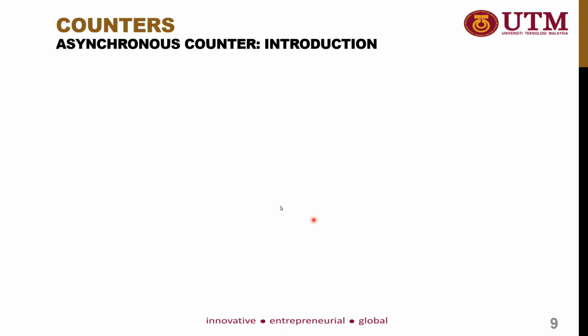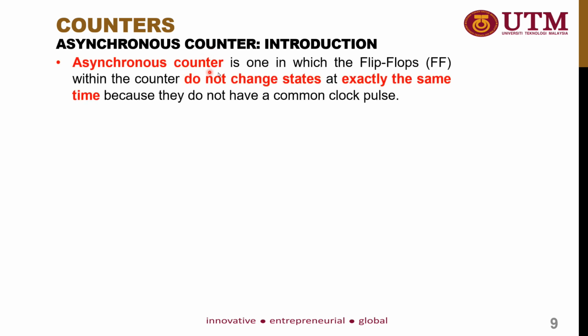So next, I will proceed to the asynchronous counter. So what is actually an asynchronous counter? An asynchronous counter is one in which the flip-flops within the counter do not change state at exactly the same time because they do not have a common clock pulse.